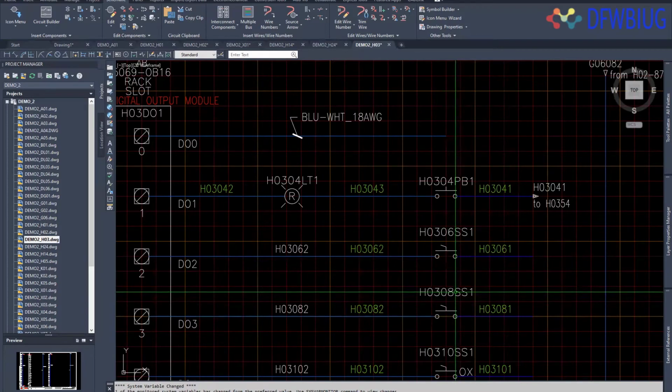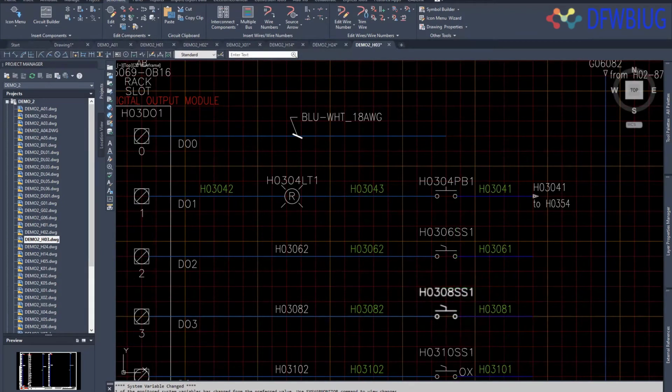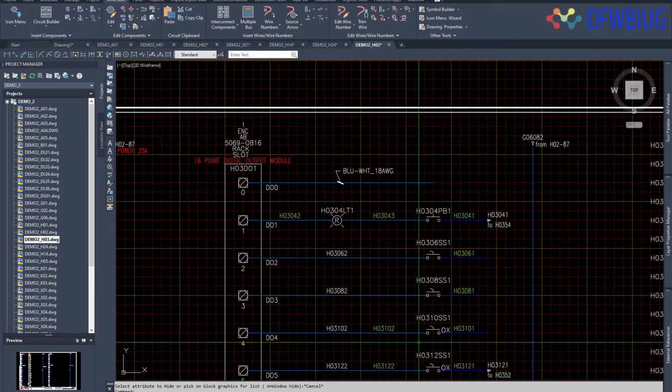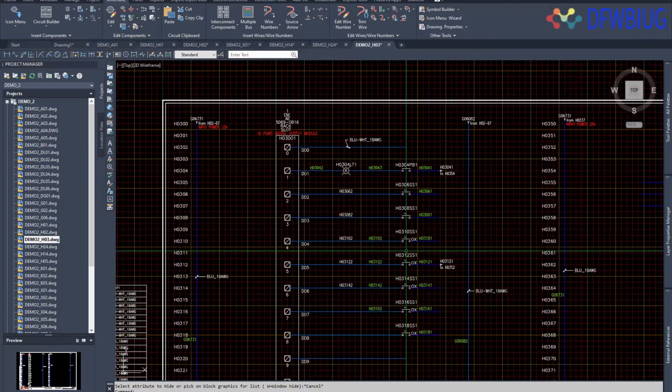People doing AutoCAD Electrical have learned it doesn't matter where I pick that attribute hide feature. I can go anywhere and I can select it, or you can type AE attribute hide. And if you want to type it, personally, I'm not a typist. I hate that. It seems like when you're hiding a small attribute within that block, and then you're selecting something else, are they grouping it together? No, it's not doing that.